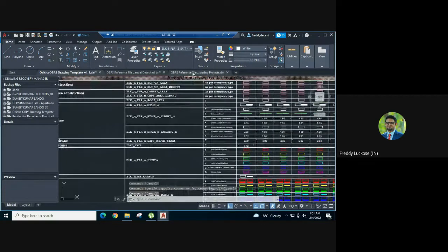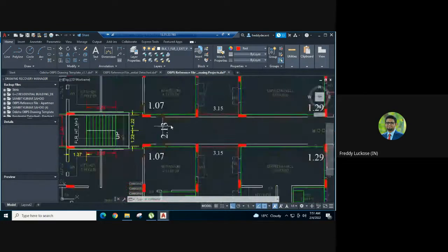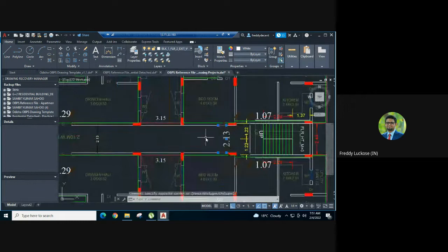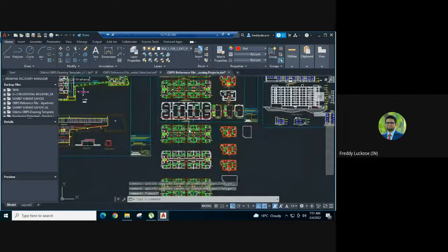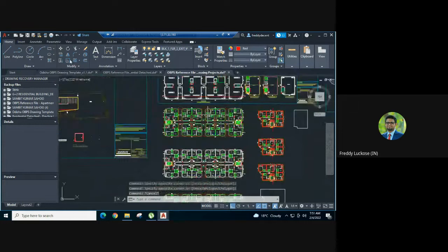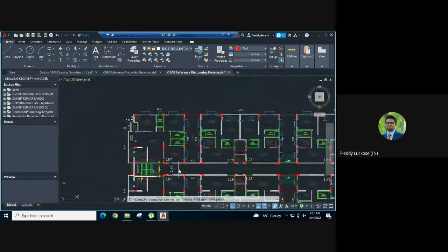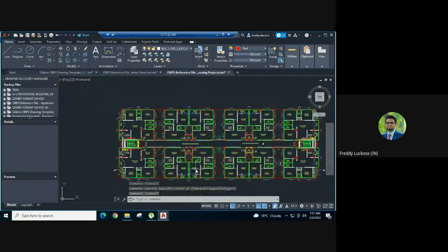If you see the reference file I've sent you, in the apartment case, I've shown two staircase exit widths. The system will count two exits, and it will also check the width provision of each. The exit width you have to show on each floor, but the travel distance you are required to show only on one floor.